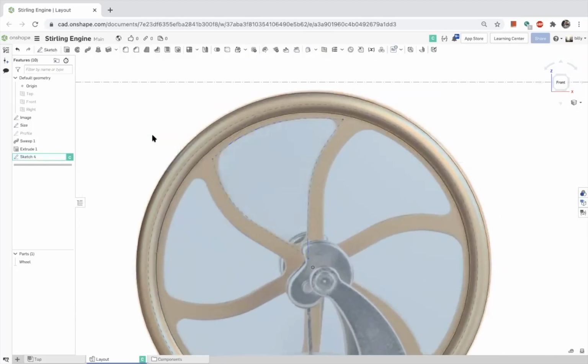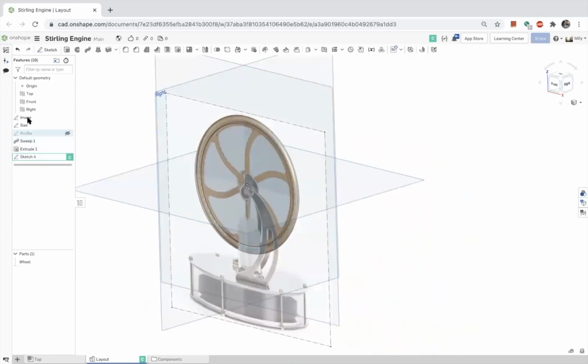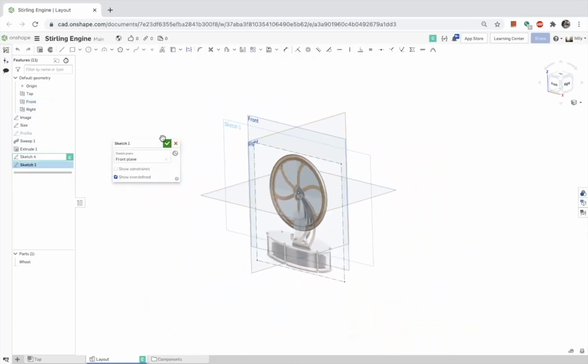Yep. Well, what about the edges? You've got to keep in mind that Onshape is solving each sketch. It'll get totally out of control if I put those arcs all in one sketch. So their sketches are free. Your existing reference was front. I'm going to create another one and keep the same reference. Okay, so now all of this stuff is on the same reference. So we can just call this arcs, and we can just call this one up here splines.